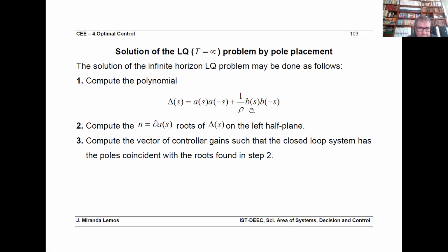So you compute these stable roots. If it is a first order problem, it's simple. You get a second order equation. If it is a second order system, then you have a fourth order polynomial. Okay, now you need to solve the roots using a computer or some mechanical computational means. But you can think that you solve it and then take the stable roots. Okay, so it's very simple.